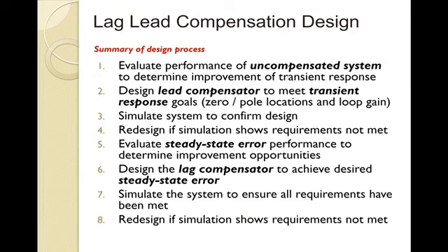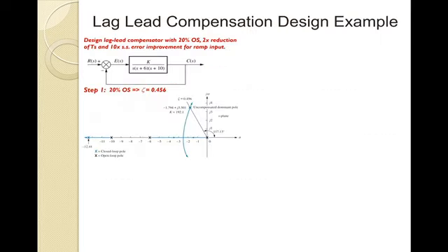So a very similar design approach where, again, for the PID, you're doing the derivative first. Here you're doing the lead first. Then you're going to do the integral term, which is essentially the lag term. And again, you're focusing on first transient, then 0 steady state error, if that's your goal.